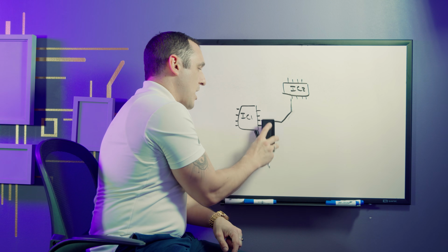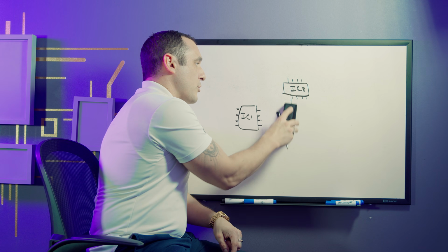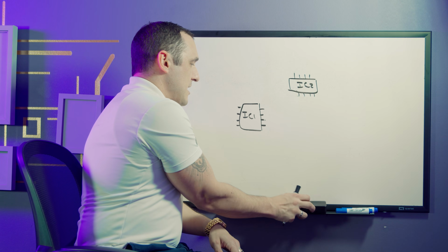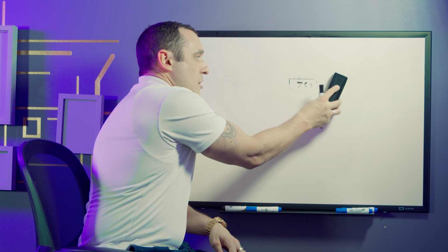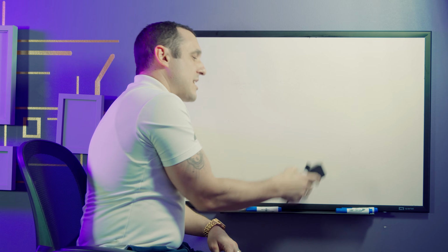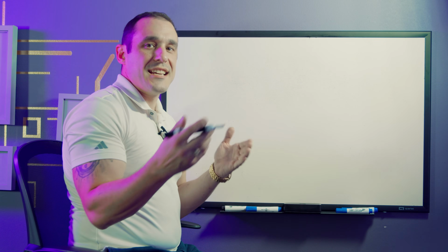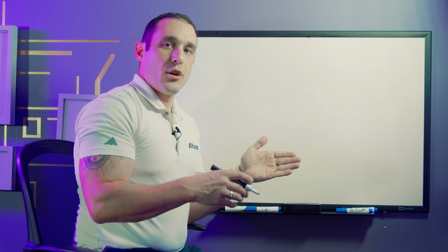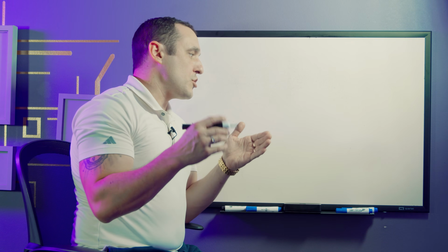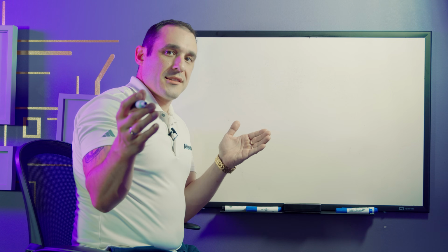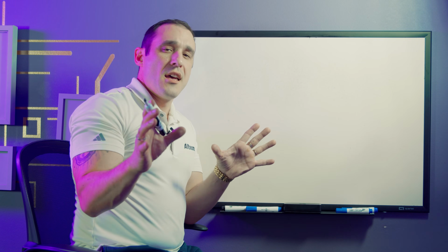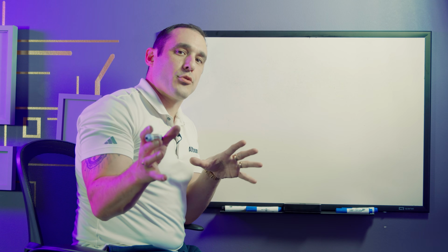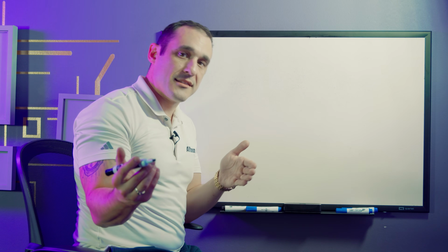What is the big objection to using 90-degree bends in these traces? Well, the big objection to using 90-degree bends in traces from the signal integrity perspective typically comes from the idea that they are going to create large reflections, or they are going to create large losses due to radiation from the trace. And I've actually seen both myths, but the most common objection to 90-degree traces is that they create huge reflections due to an impedance discontinuity.